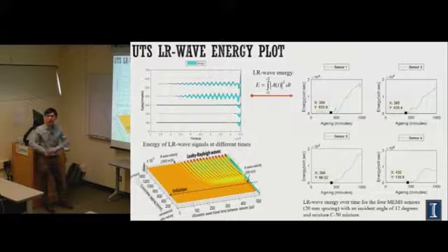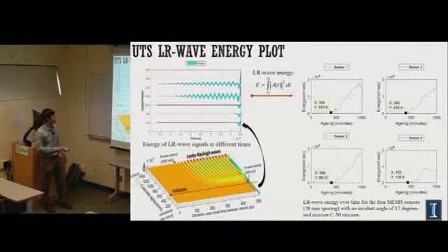So if I stack all the signals together, then I will see that, firstly, when the concrete is not yet set, it doesn't have enough strength to hold the shear from the wave, then we don't see any signal. But after that, when the concrete sets, it develops sufficient shear strength, then the wave appears and leaks to the air. That's why we capture it. So you see over time, the signal will be clearer and clearer.